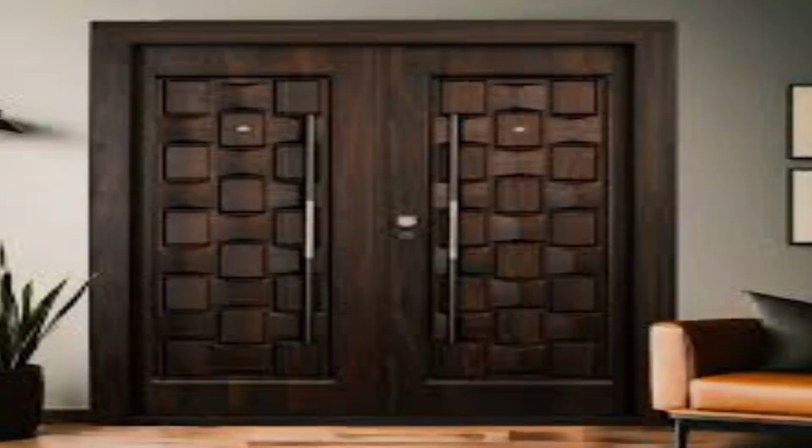Next comes the doors, windows. We are not using ventilators these days because buildings are designed to have ample cross ventilation. So ventilators are not used these days. Please keep it in mind. But with the doors and windows, doors are for security, windows are for bringing in the sunlight and air. So you can use wooden, PVC, aluminium, and a lot of other innovative materials have also come up for the doors and windows. The placement of doors and windows depends on the design, and for a very efficient design, doors and windows should be placed in such a manner that there is enough cross ventilation and air coming into the house.